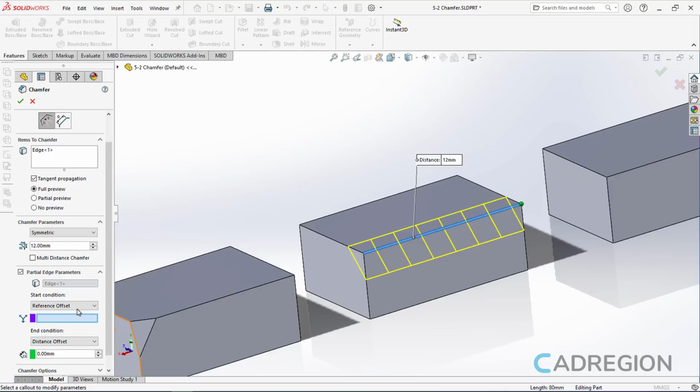In this example, I will expand the start condition list and I will select the distance offset option. Then I will type the number 20 in the offset distance 1 field and I will press enter. Notice that the chamfer starts 20 mm to the right from the beginning of the edge.